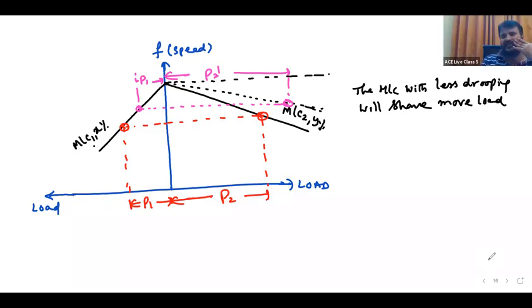Good. That is what I told you. You are exactly correct. But in this case, if you look at the droop characteristics, as load is increasing, frequency is reducing, no, sir? And that will definitely occur. These are the original characteristics of the turbine. The drooping characteristics we are taking are the characteristics of the turbine. When load increases, its speed has to reduce. But both will settle at some particular frequency. Both have to be settled at one particular frequency.